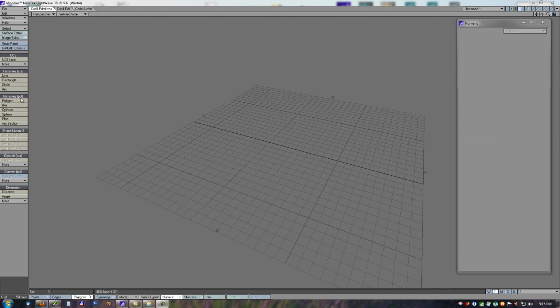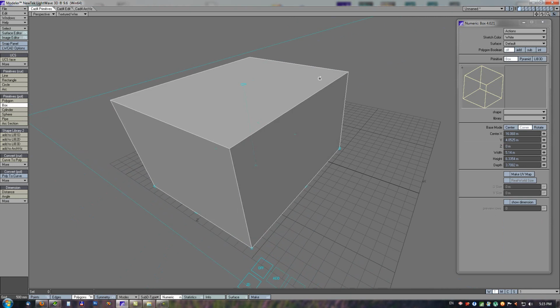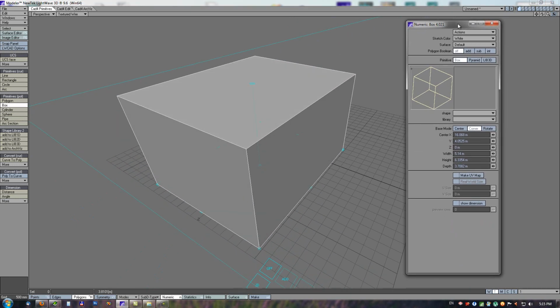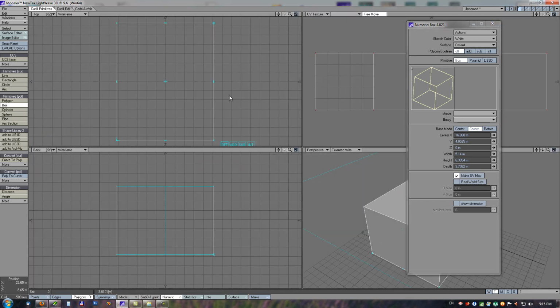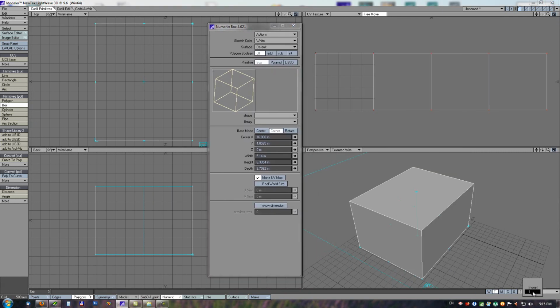The biggest change for primitive tools in this version is UV mapping. Every primitive tool, or every tool which deals with polygons, can now enable UV maps. When UV maps are enabled, if there was no UV map in the scene before, a new UV map with the name 1 is created automatically. Or if there was any previous UV map selected, then the tool will use that selected UV map.